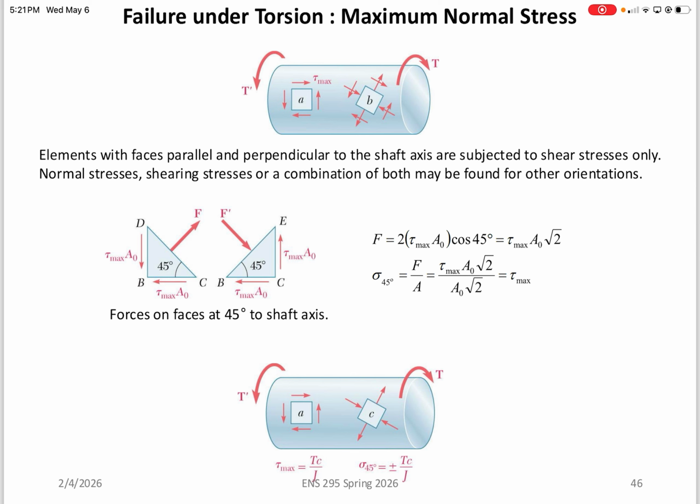You can also have cases where it's combined torque and axial loading or even bending, in which case you would need to characterize tau xy, tau xz, tau yz, and then do what we did early on in chapter 7 using Mohr circle 2D and 3D principles to calculate the normal and shear stresses. But as long as it's not within a plastic region, you can observe all of the linear elastic regions. The trick becomes applying which stress to which.